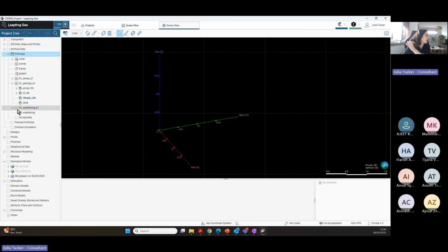So now you can check that the errors that we have on the weathering had gone, because what I wanted to show you is that when we are appending data, we are appending in the same drill holes. If we want to import more drill holes, we will have to import it and reload it. And now we were getting that error. If you check the video before, you will see that that error was caused by the lack of information of whole ID.